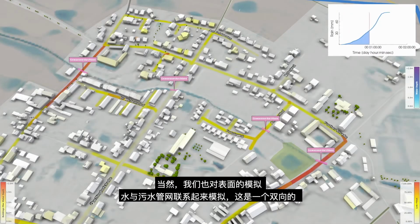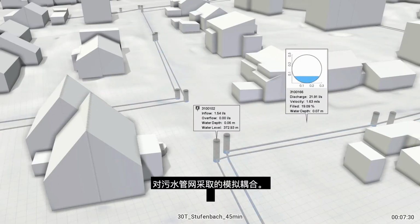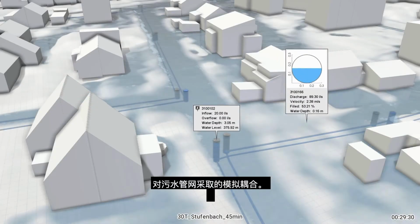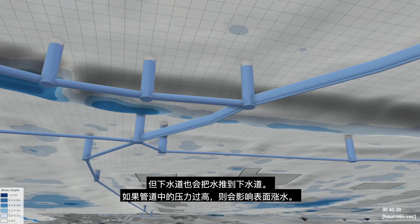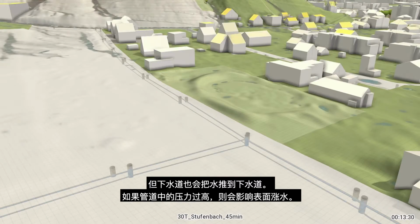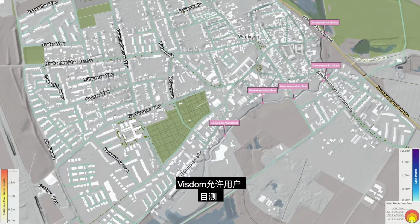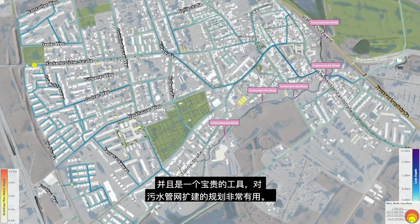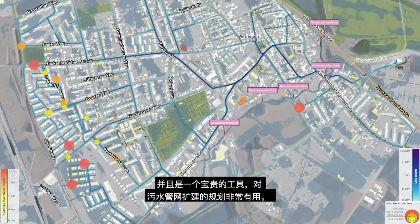Of course, we also couple the simulation of surface water with the sewer network. This is a two-way simulation coupling where the sewer network takes up water from the surface through storm drains, but the sewers can also push out water to the surface if the pressure in the pipes is too high. Visdom allows the user to visually explore such situations and is a valuable tool for the planning of sewer network expansions.